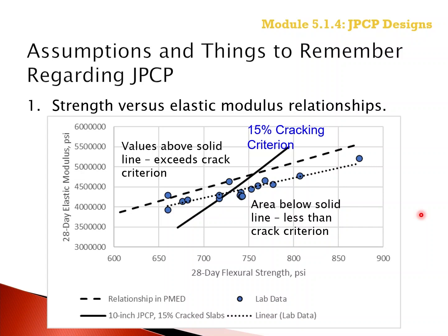Conversely, if the concrete strength and elastic modulus relationship embedded in the PMED software was used for calibration, in other words, the PMED relationship or regression equation between strength and modulus was used for calibration, then that relationship should be used for design.